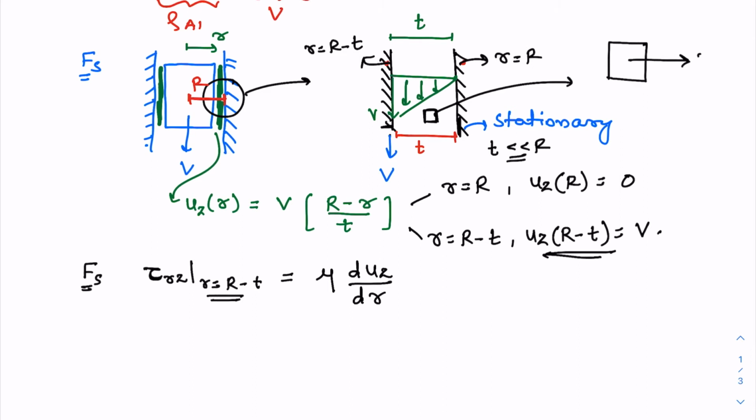So if I focus on a small fluid element in this film, this is direction R, this is the Z direction. So the shear stress acting on these vertical surfaces, by our sign convention and the convention for notation for the stress, acts in these directions and is denoted by tau rz.